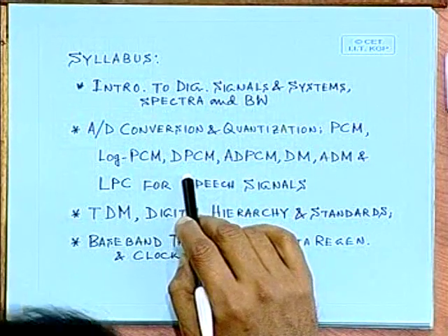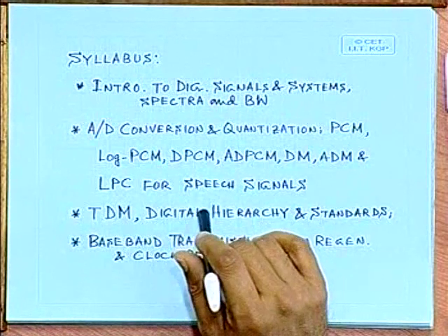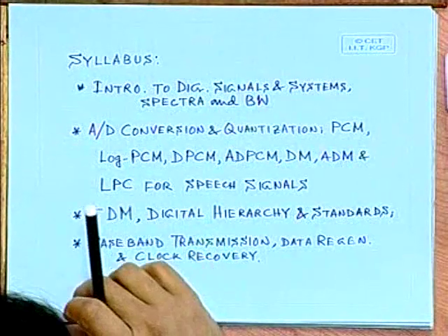An advanced version of DPCM is known as ADPCM, or adaptive differential PCM. We will have a unit in a PCM coder and decoder which we will call a predictor. If this predictor can adapt itself depending on the temporal nature of the input signal samples, then the process of differential pulse code modulation is even more effective or efficient, because it reduces the transmission bit rate further, probably without compromising the signal quality. So ADPCM is a more advanced and more effective version of DPCM, but there will be some limitations in the form of complexity of the coder and decoder. We will have some discussion on ADPCM.